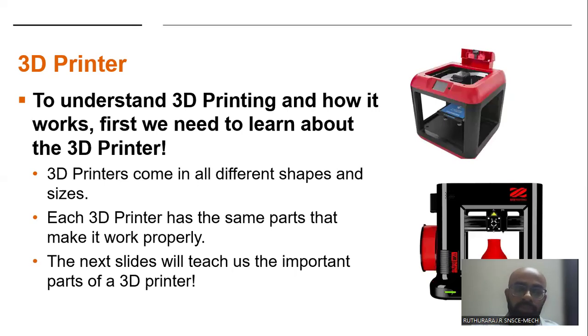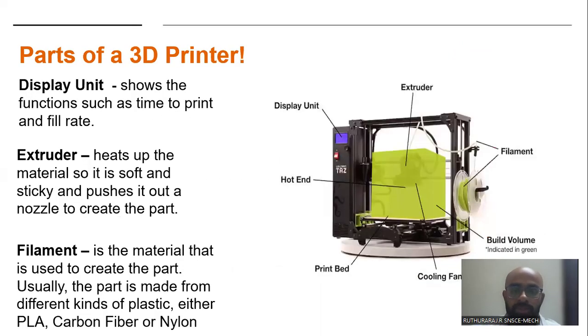In the printing process, as you can see here, this is a plastic 3D printer. Here spools of plastic will be utilized. The plastic may vary; we may use ABS, polyethylene, terephthalate, PET plastic, any type of plastic depending upon your need. Spools of plastic will be available that will be melted and deposited in a layer by layer manner. As you can see here, these are the basic filaments. This is the filament roll I was talking about.